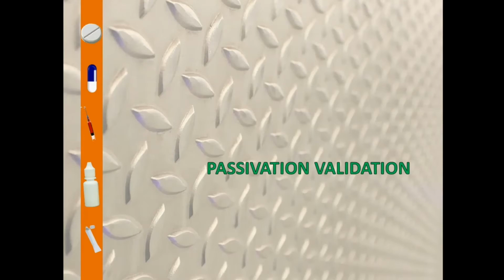I have frequently seen in the pharmaceutical industry in North America that the passivation process meets a standard and passes a peroxide test. These two features underpin the validation process. However, demonstrating cleanliness required by the industry nowadays will require a deeper understanding of the standard and a more sensitive testing than the peroxide test.